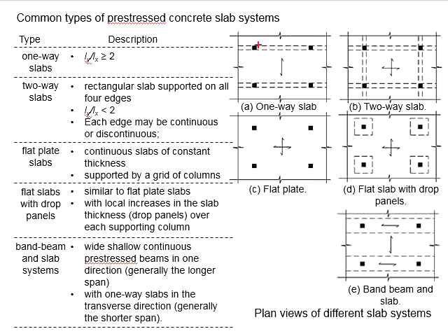The figure here shows a typical one-way slab, where the arrow indicates the directions of the loads being transferred within the member, which is only in one direction to the adjacent beam. When there is beam only in one direction, the load acting on the slab will automatically go to the adjacent beam, and this leads to a situation that the load is transferred in one way for this one-way slab.